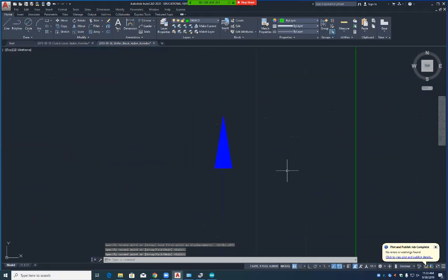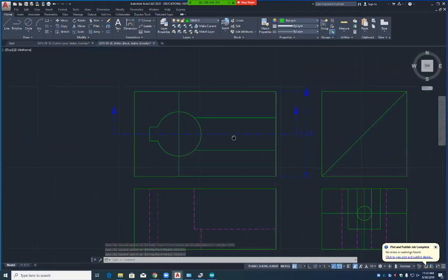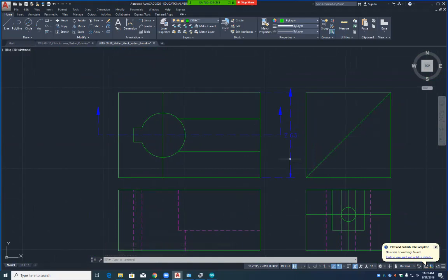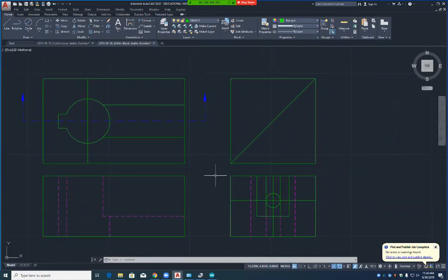Okay, now, what this is telling me, the arrows tell you the direction you're viewing. So, if I were to draw this right here, this is my top view right here, isn't it? My front view right here. The arrows say that I'm removing this bottom half and I'm viewing that from here up. Does that make sense? And so my front view now, I'm going to rotate that down like that, and I'm going to draw what I see now from my top view and my front view.